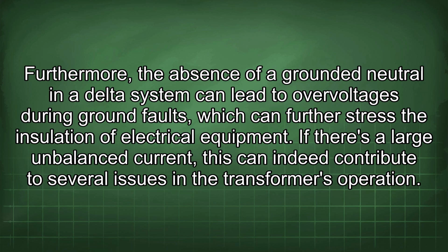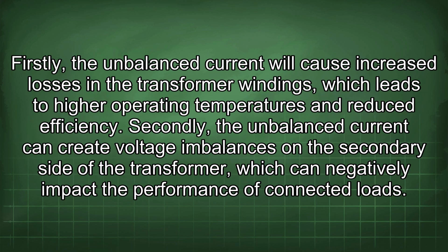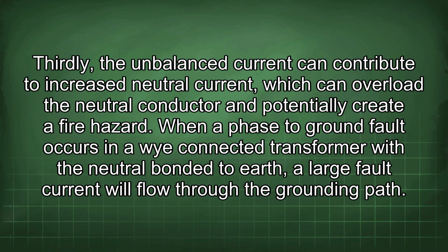If there's a large unbalanced current, this can indeed contribute to several issues in the transformer's operation. Firstly, the unbalanced current will cause increased losses in the transformer windings, which leads to higher operating temperatures and reduced efficiency. Secondly, the unbalanced current can create voltage imbalances on the secondary side of the transformer, which can negatively impact the performance of connected loads. Thirdly, the unbalanced current can contribute to increased neutral current, which can overload the neutral conductor and potentially create a fire hazard.